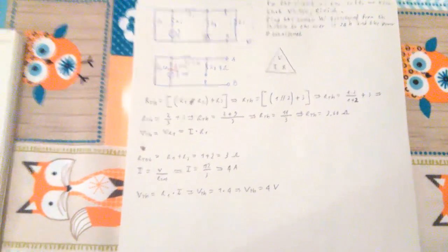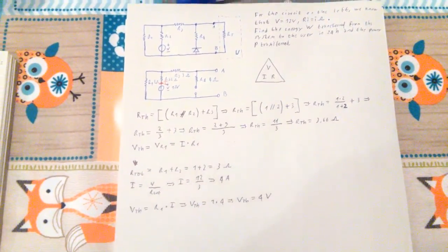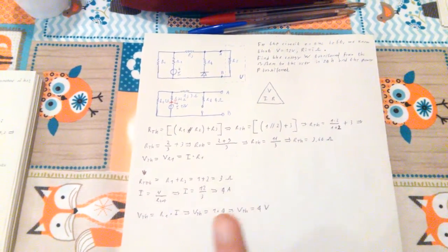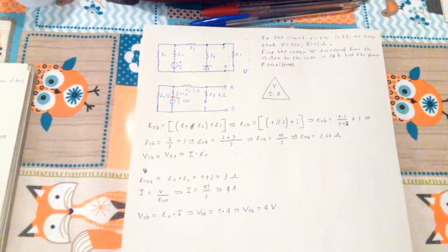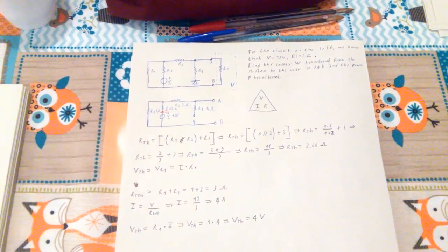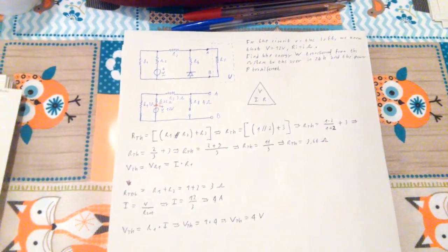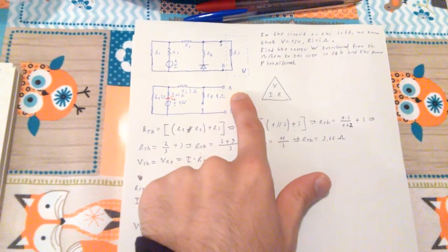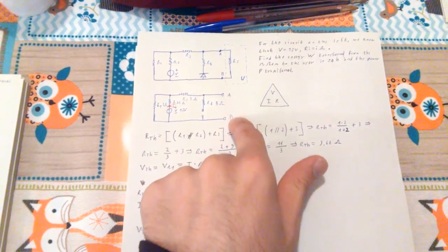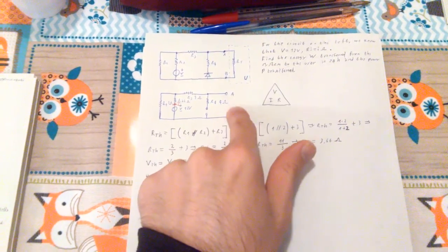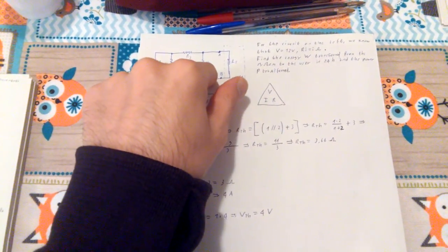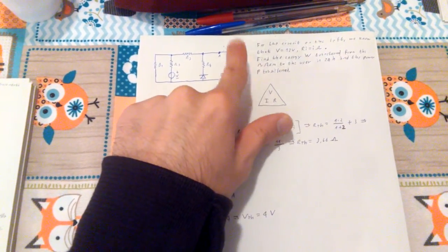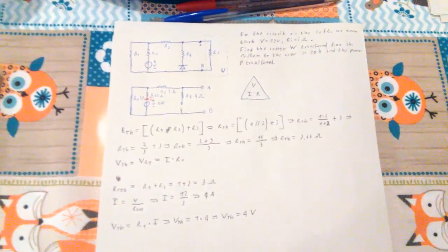Now, we have found RTH, the Thevenin resistance, and VTH, which is the Thevenin voltage. So we are getting there. Now we can actually draw the Thevenin equivalent circuit at points A, B. But since I actually did it for those 2 points A, B in the original circuit, I'm also going to add the user, which is this part here, with the resistance R5.